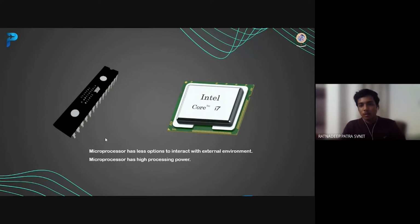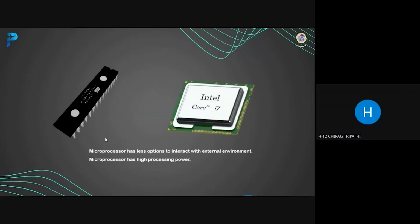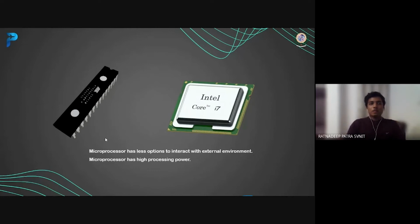So moving forward. Sir, is there any particular merit of a microcontroller over a microprocessor? Merit in the sense that several input output options are built in to a microcontroller. If you are programming a microprocessor, you even have to write code for performing simple ADC operations, but in a microcontroller you can just directly use its built-in feature.